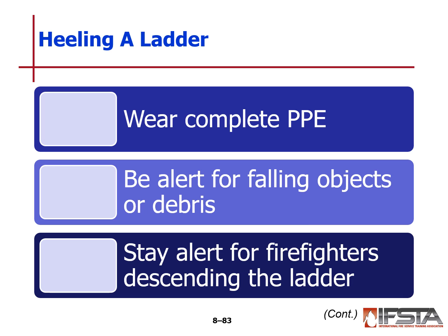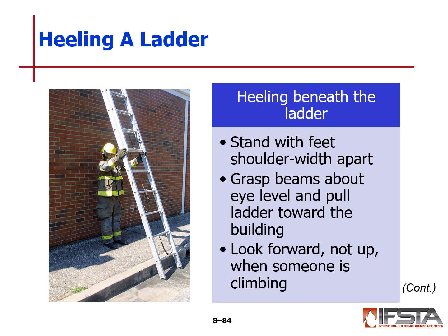If you are heeling a ladder, please wear complete PPE, including your helmet with your face shield down. Be alert for falling objects or debris. Stay alert for firefighters descending the ladder. When you heel beneath the ladder, stand with your feet shoulder width apart, grasp the beams about eye level, and then pull the ladder towards the building. Look forward, not up, when somebody is climbing. I'm not a big fan of heeling a ladder this way, but when you're in close quarters, small alleys, and in tight areas, you may have to use this technique.